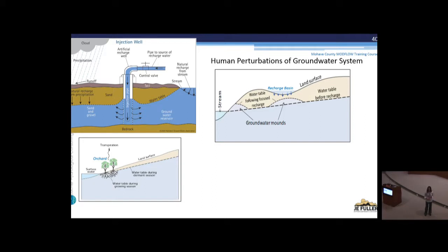That could mean still 50 feet down if it's a 300 or 400 foot thick zone, but you've got to be able to see in your meaningful time period your water get into the groundwater zone. And if it takes 50 years for it to percolate to the groundwater zone, don't expect to be using it until that happens.